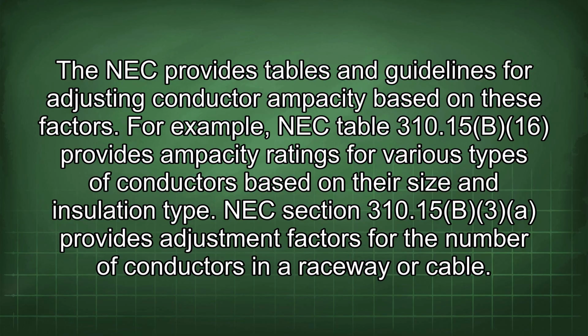For example, NEC Table 310.15(B)(16) provides ampacity ratings for various types of conductors based on their size and insulation type. NEC Section 310.15(B)(3) provides adjustment factors for the number of conductors in a raceway or cable.